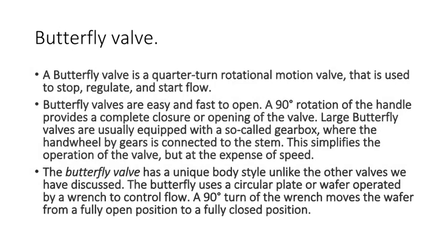A butterfly valve is a quarter-turn rotational motion valve that is used to stop, regulate, and start flow. Butterfly valves are easy and fast to open. A 90 degrees rotation of the handle provides a complete closure or opening of the valve. Large butterfly valves are usually equipped with a so-called gearbox, where the handwheel by gears is connected to the stem. This simplifies the operation of the valve, but at the expense of speed. The butterfly valve has a unique body style unlike the other valves we have discussed. The butterfly uses a circular plate or wafer operated by a wrench to control flow. A 90 degrees turn of the wrench moves the wafer from a fully open position to a fully closed position.